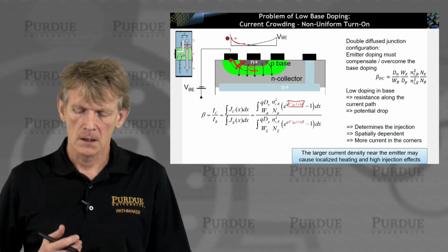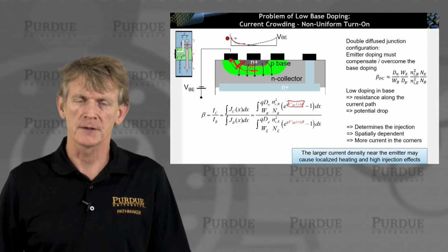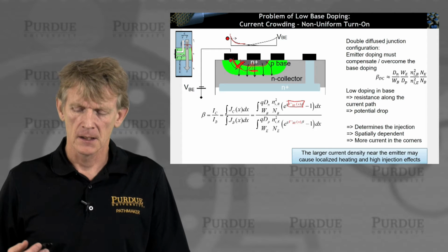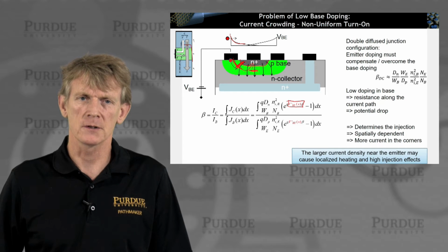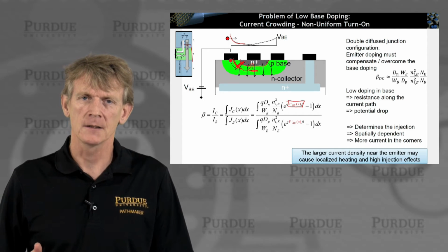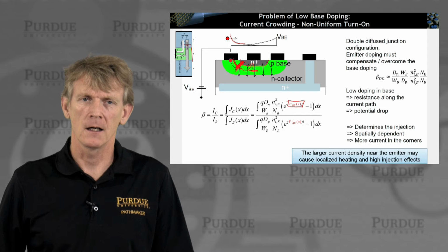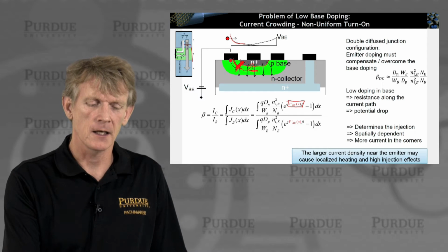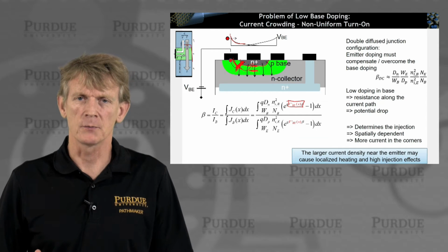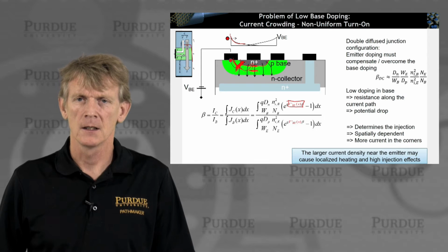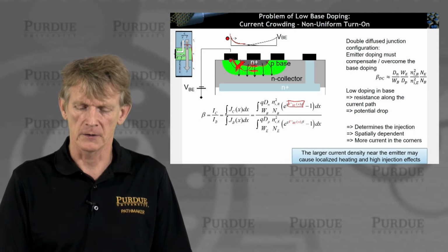So, as I just stated, if you have an inhomogeneous electrostatic potential like this, you will have unequal, non-homogeneous current distributions, and that means you might have current crowding, and you might drive components of your current to a very high intensity versus other areas have low intensity. So you will operate the device in different regimes, so to speak, high current versus medium current regimes. You will have temperature gradients, all kinds of things could break loose in this kind of configuration.